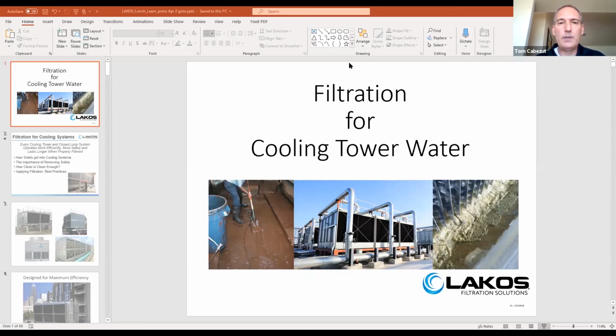Next is Kevin Lynch, who is a rep out of Southern California. Thanks, Kevin, for listening in. He works with the vertical systems guys. And his question is, if you have a single TCI serving multiple closed circuit fluid coolers, do you need to equalize those coolers too? The answer would be yes.